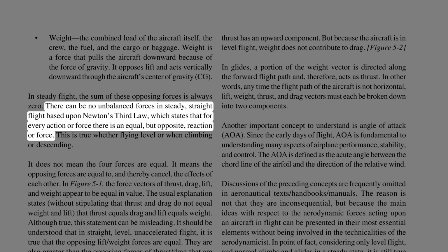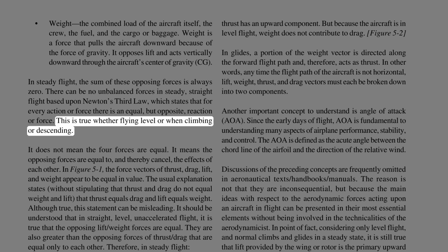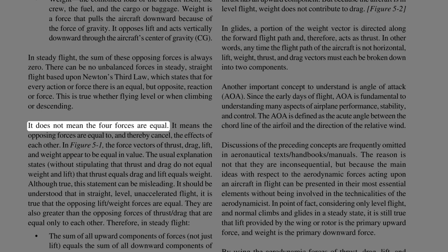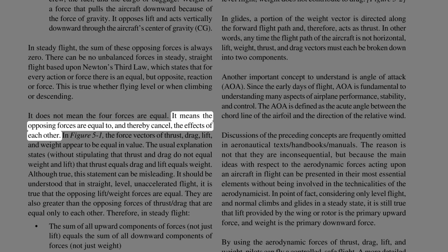There can be no unbalanced forces in steady, straight flight based upon Newton's third law, which states that for every action or force there is an equal, but opposite, reaction or force. This is true whether flying level or when climbing or descending. It does not mean the four forces are equal. It means the opposing forces are equal to, and thereby cancel, the effects of each other.